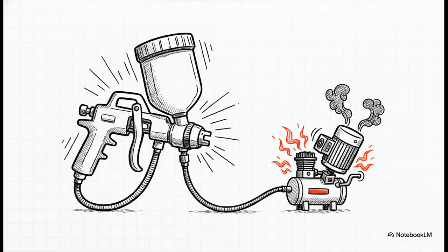When they do that, the volumetric efficiency drops from 85% down to 75% because those internal reed valves simply cannot snap shut fast enough. They still only get about 9 CFM, the pump head temperature spikes to 195 degrees Celsius, and the pump completely destroys itself. It's proof that you can't just slap a bigger motor on an undersized compressor head, you need a bigger pump, period. Or at least a much larger storage tank.